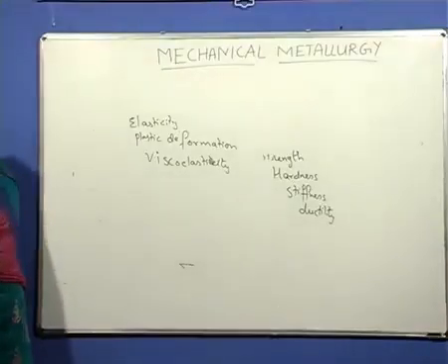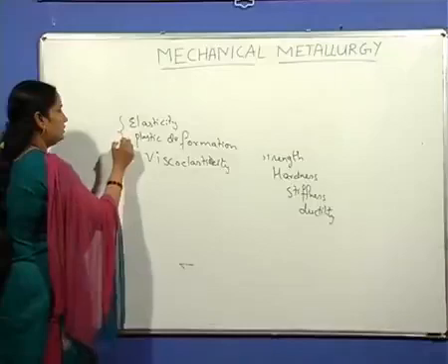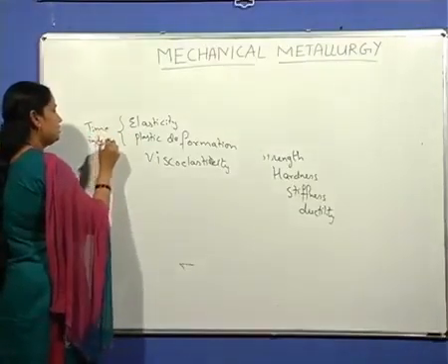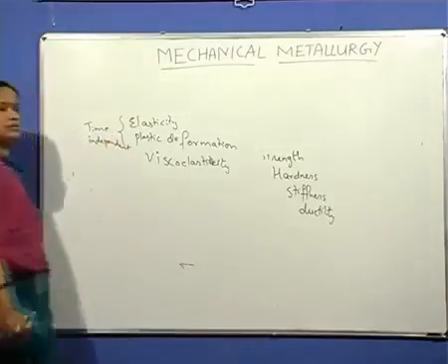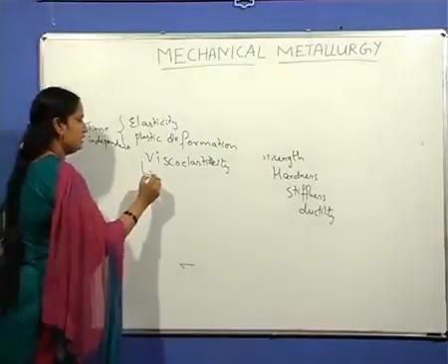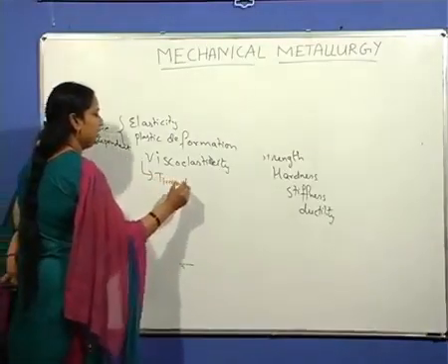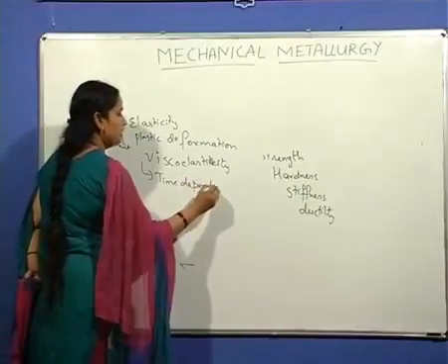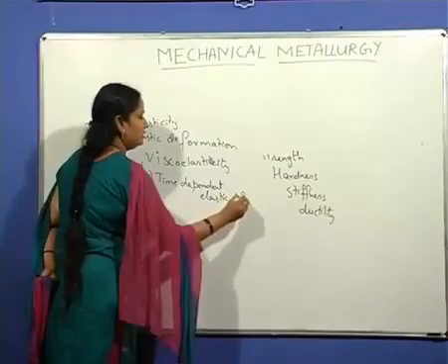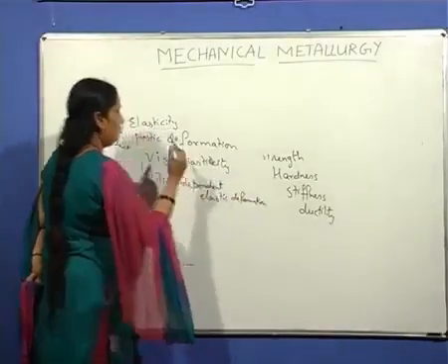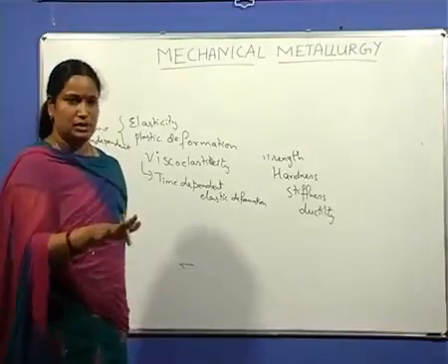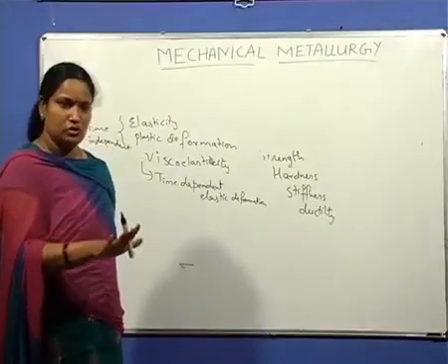That is elastic deformation. These are time independent deformations. They have nothing to do with time. Whereas viscoelasticity is time dependent elastic deformation. Plastic deformation is, upon the application of load, the material undergoes plastic deformation, some extent of shape change.